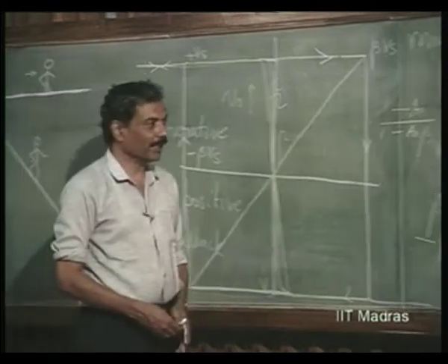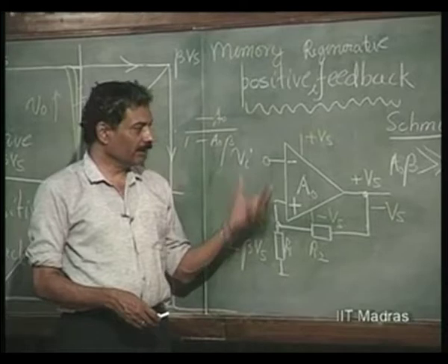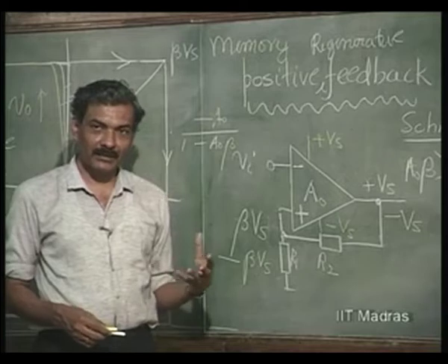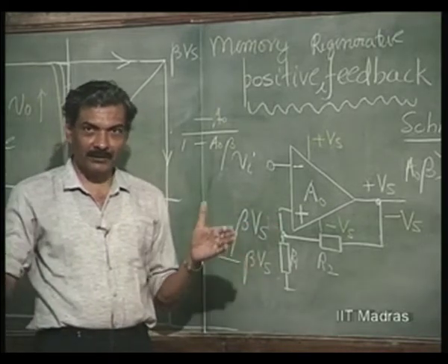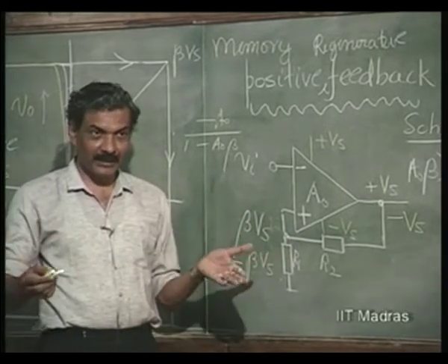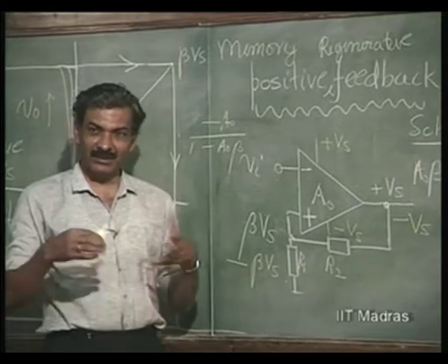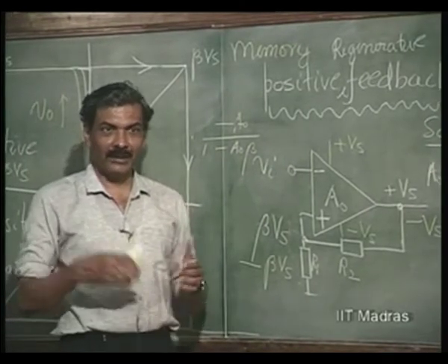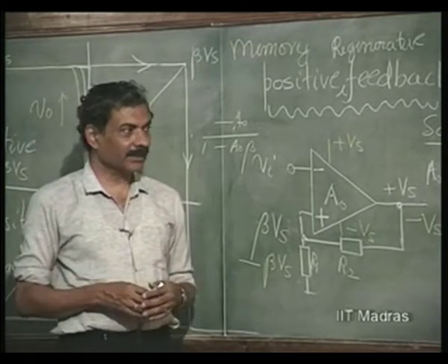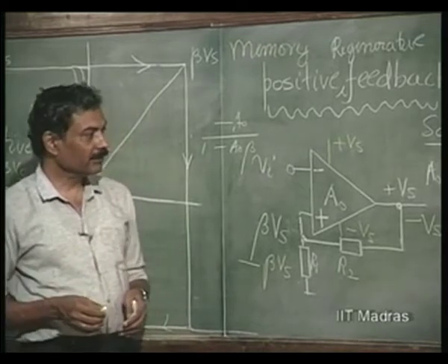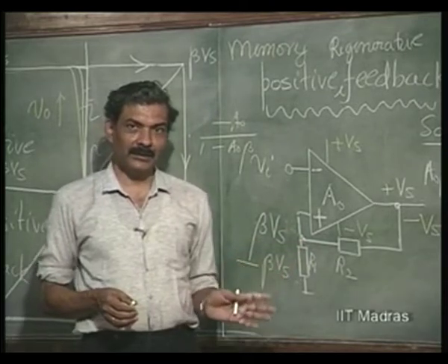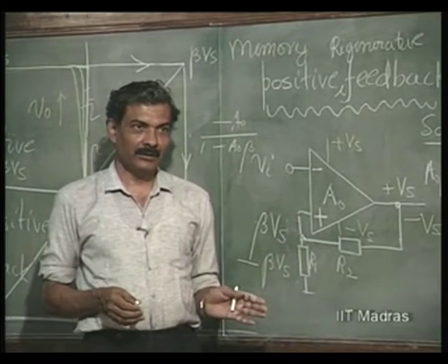This particular circuit has numerous applications in digital circuits for wave shaping, where you have data transmitted in terms of ones and zeros. This data, when it is transmitted through the cable, gets distorted because of the distributed effect of capacitors, etc., and gets attenuated, and therefore gets distorted, and you want to reshape it so that the transitions of the pulses become very sharp.